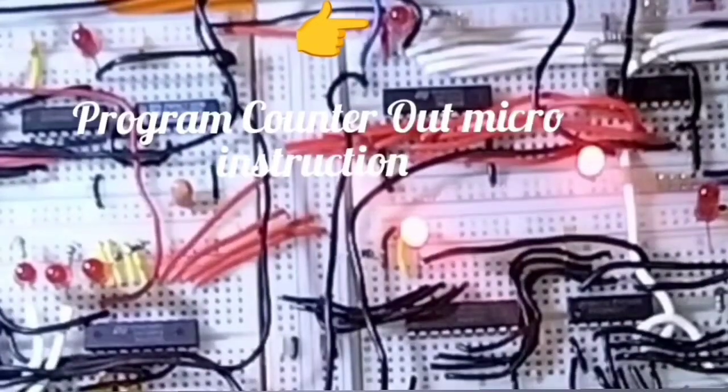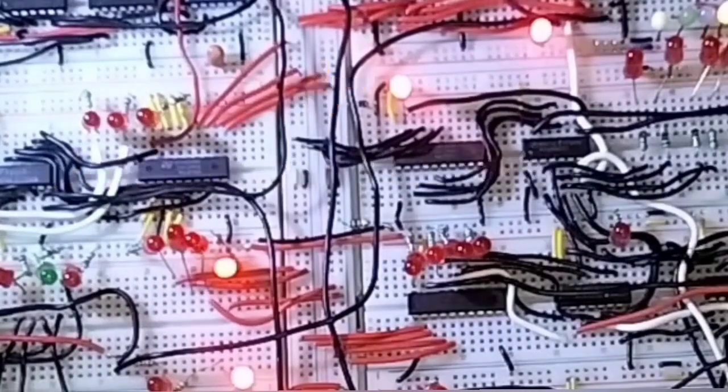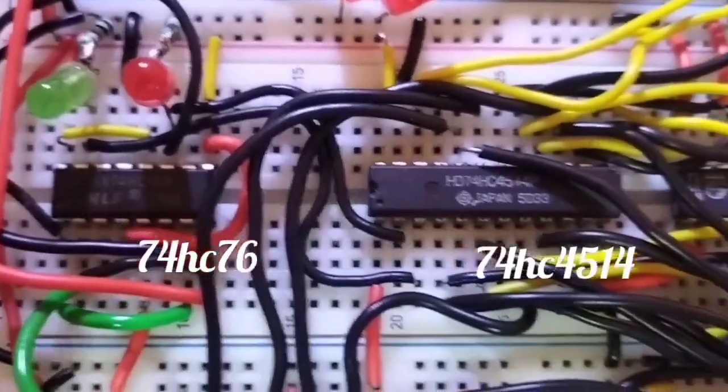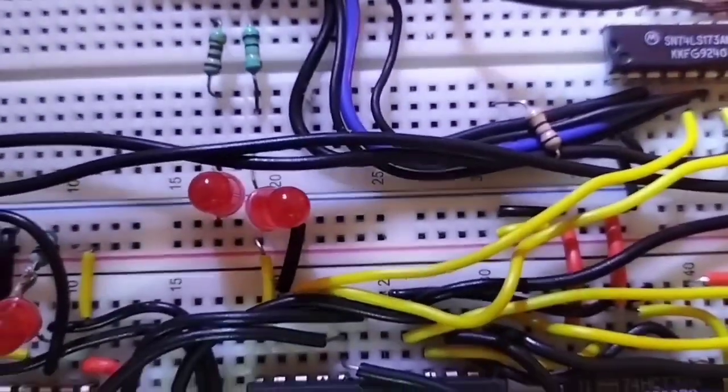Program counter out, memory address register in, RAM out, A register in, B register in, ALU out, output register in, instruction register in. All these micro instructions are active low except program counter increment enable.